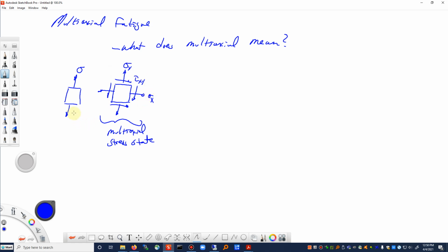If all of our stresses were uniaxial, like in the first picture, then we would pretty well expect the cracking plane to be perpendicular to that stress direction. The initiation plane might be at 45 degrees to the axis, and I'll also point out that that could be a 45-degree in-plane or a 45-degree out-of-plane initiation for maximum shearing stresses and strains. Now here's something that's kind of interesting.